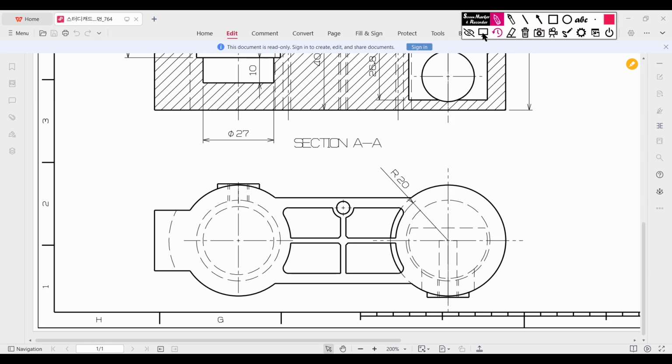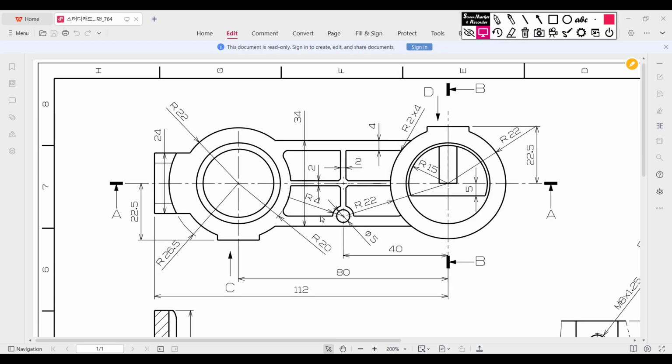So for that in our sketch here, first of all I will draw a center line here, and from the center line I'll draw a 4 radius circle, this outer semicircle portion. Okay, 4 radius semicircle portion. Then I will extrude boss it downward. Then this portion will be filled solid, and from that solid filled portion I'll again draw a center line here, then draw a circle, and this time the circle has a radius of 5 unit. This time I'll do the extrude cut portion.